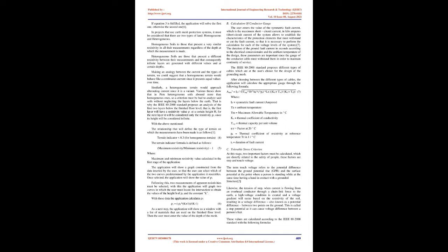The user enters the value of the symmetric fault current, which is the maximum short circuit current, in kiloamperes. Short circuit current of the system allows to establish the characteristics of the protection elements that must withstand or cut the fault current, so it is necessary to perform the calculation for each of the voltage levels of the system.